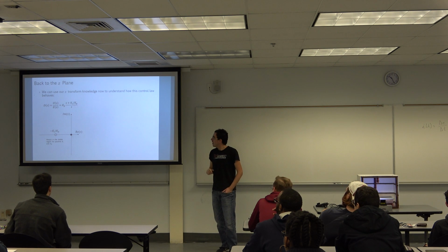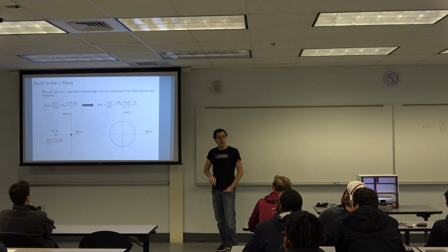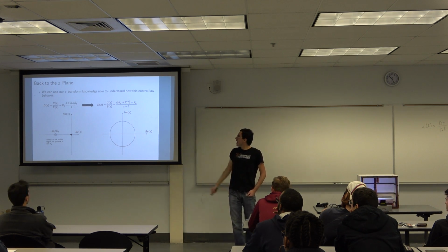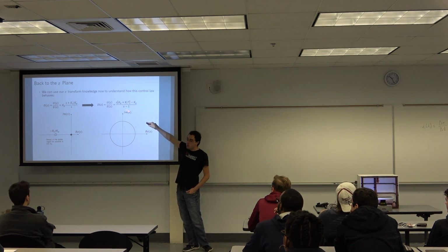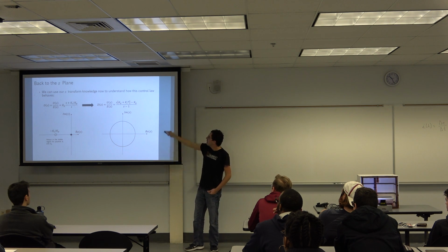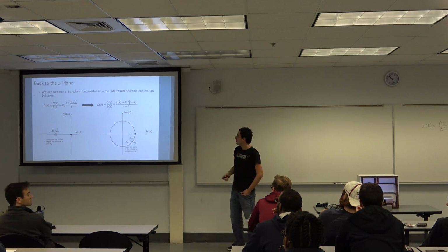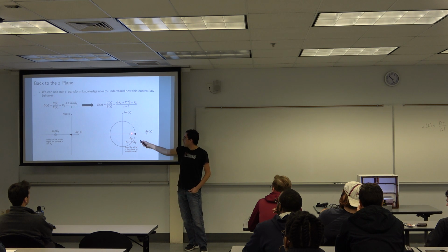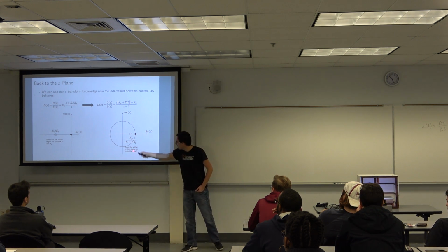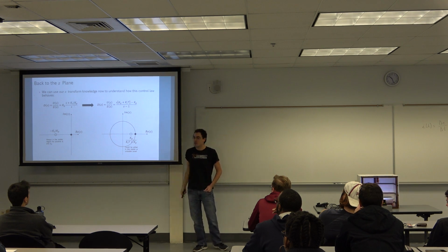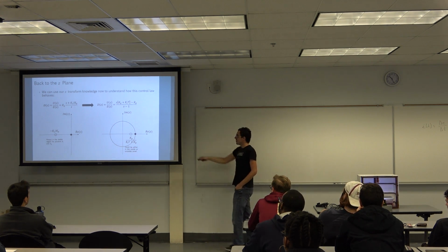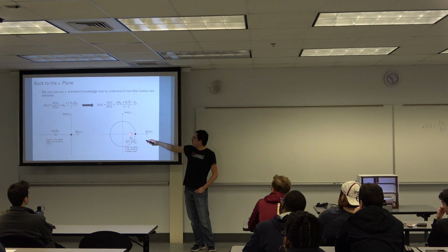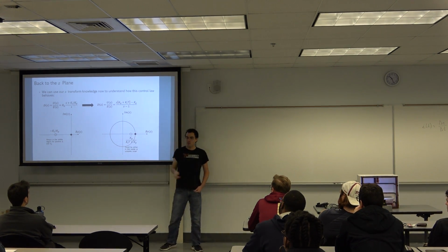So now we can do the same for our D of Z, which is our controller in the discrete domain. And if we do that, we get this expression where the pole is exactly at +1. And the zero lands at, well, you make this expression equal 0, and then you find out where it is. It's kind of a nasty expression. But it always lands inside of the stable zone as long as you have positive Kp in here. But the expression is correct. This pole here moves around and it always stays between 0 and 1.